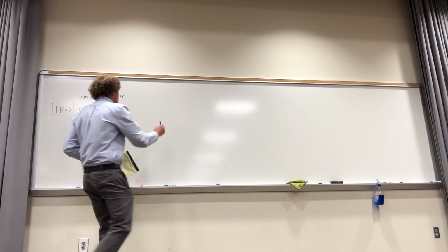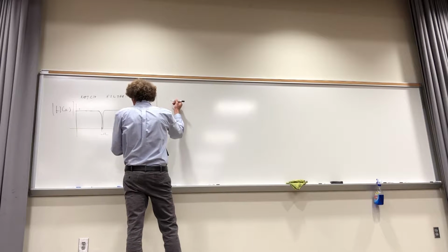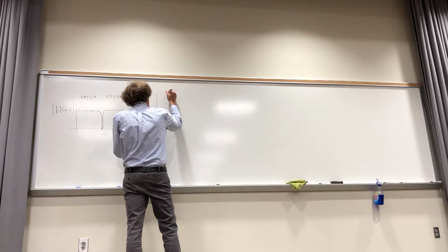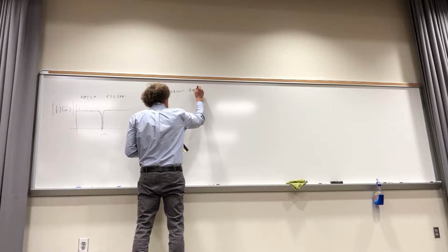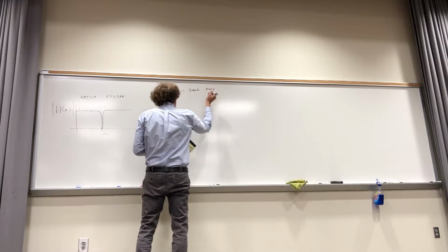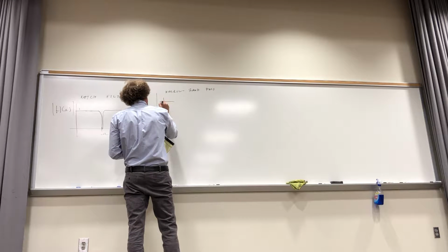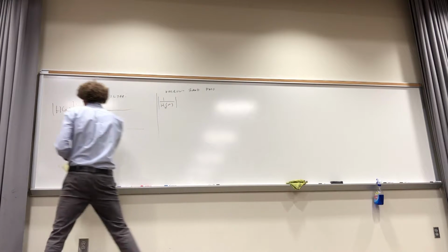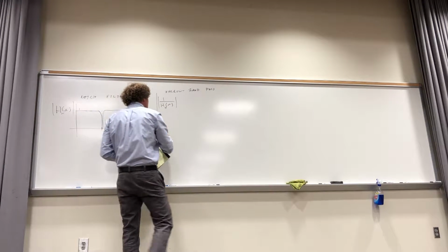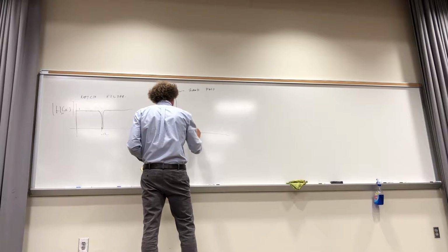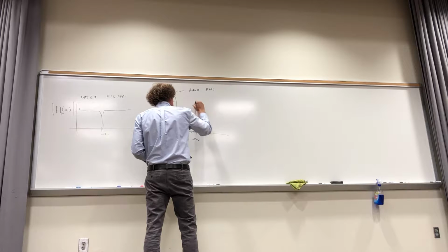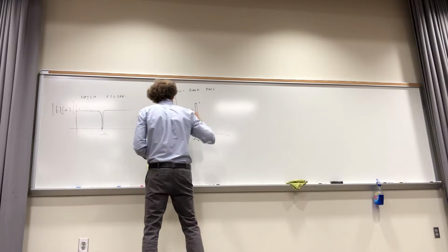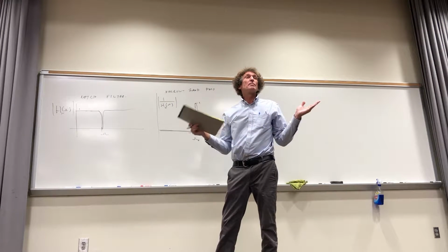So if you wanted a very narrow band pass filter, you would take 1 over h of omega of the notch filter, call it h of n, that being notch. And then you would get this. You would basically kill everything except at the notch frequency, and then you would get this. Follow me? You would only pass that frequency.